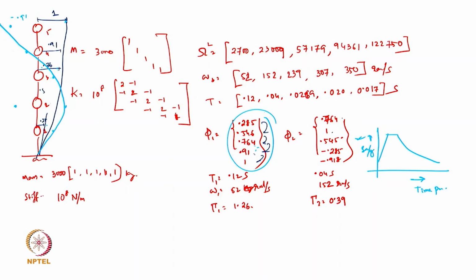Now think that you are getting a time period of 0.12 second. So you can just pick the point corresponding to 0.12 second. Whatever the Sa/g is coming, you pick it up. So you can say that that is my Sa/g. Fantastic. And that Sa/g you can multiply with the modal participation factor, whatever the factor is coming, then it tells you how much is actually coming on that. Okay.